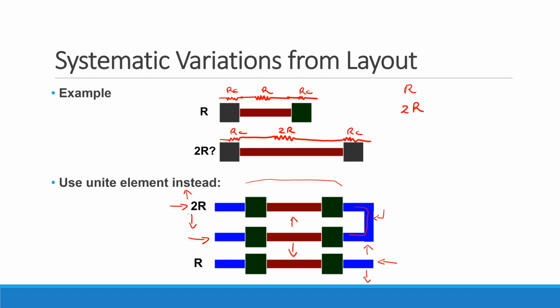So in this particular case here, if you have something where at the end there's a bunch of blank space around it versus things that have a lot of poly nearby, the speed at which you do that etch actually changes. So what you'd really get, potentially at least in this particular example, is 2 thin lines that are etched a little bit more and 1 thicker line in the center. Okay? And again, it just has to do with it not being exactly the same. So even when you processed it, things ended up being a little bit different. Okay? Does this make sense to people?